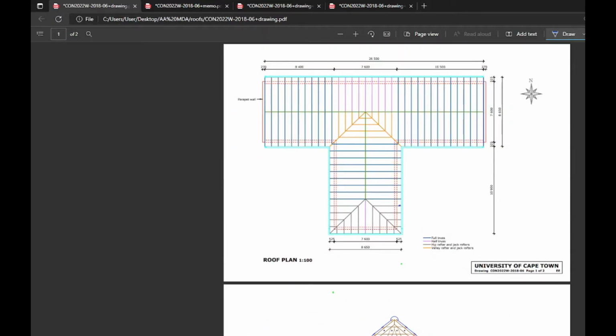It's by itself, slightly unsupported, and it's going to sort of piggyback onto other structural members. So our jack rafter, that's our drawing. We've got our walls, and it's going to be fixed with hoop iron, and we're not going to describe how it fixes to the rest of the roof structure. So we do not elaborate on how it fixes to this rafter, the hip rafter. We don't expand on how it fixes to the valley rafter.